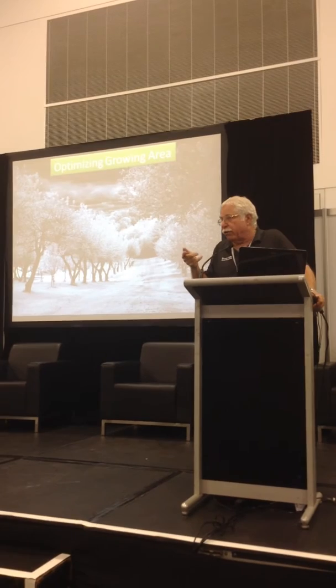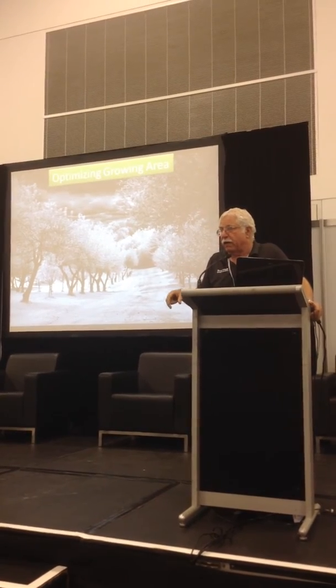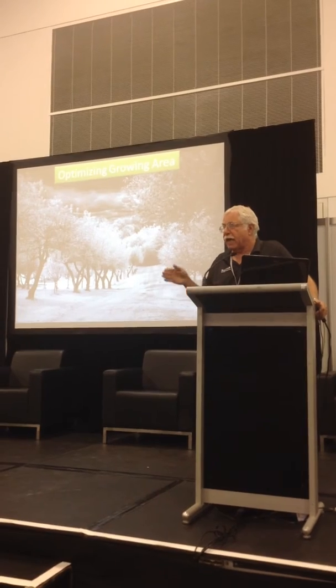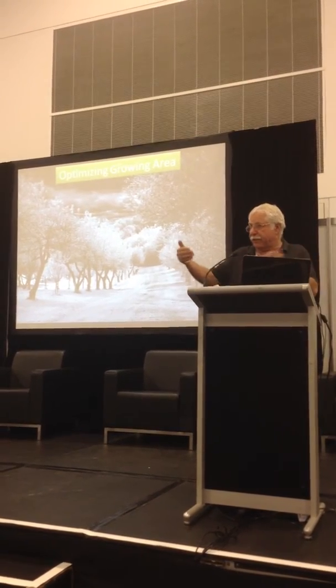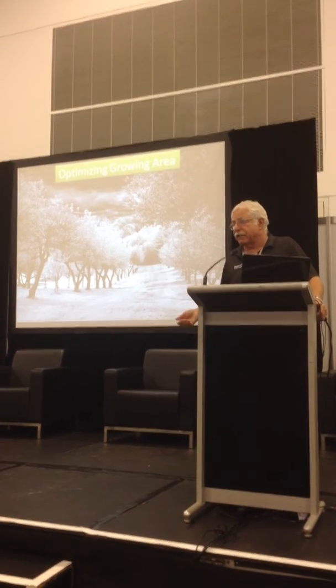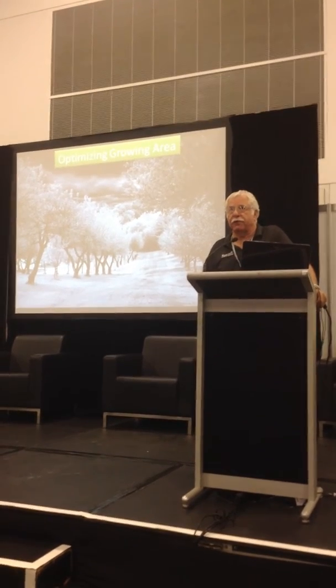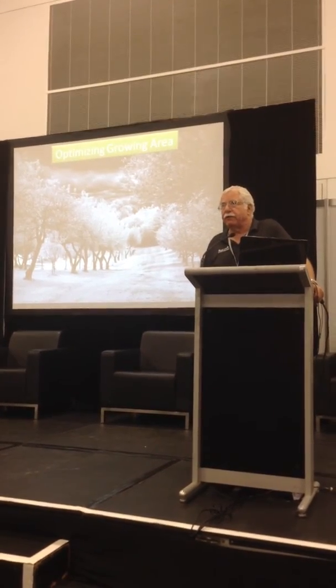If you see a road embankment, for instance, with a gentle slope of 1 or 2 or 3% hitting that road embankment, and the embankment is 2 meters high, if you look at the frost line around that vineyard, you may see that it might be 4 meters high or 6 meters high. If you draw a straight line across it and down, you'll see the relationship is 1 or 2 or 3 times the height of that barrier. That's the potential based on how much cold air is coming in, and at some point it has to flow out. So we want to identify where your cold air fluxes are coming in, and we want to try to limit those.